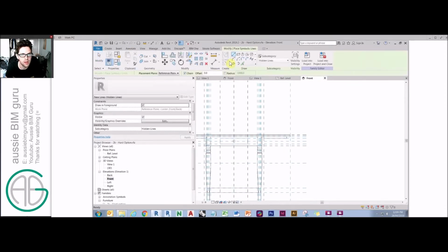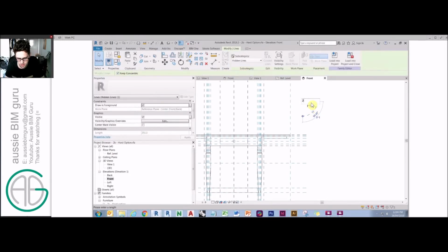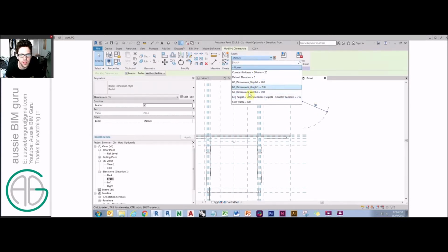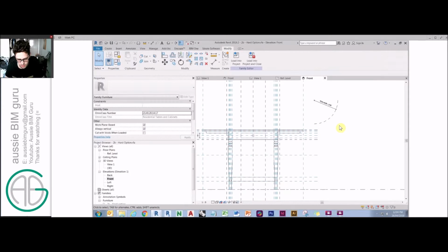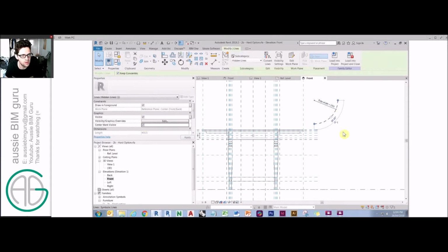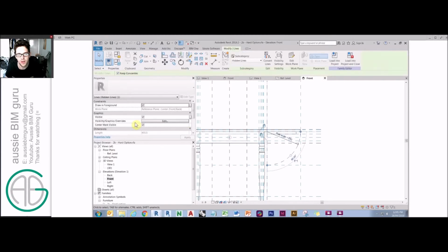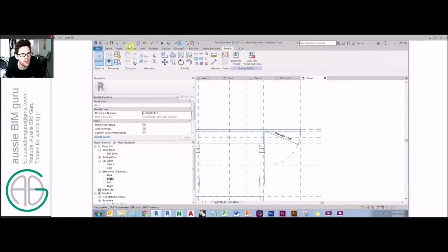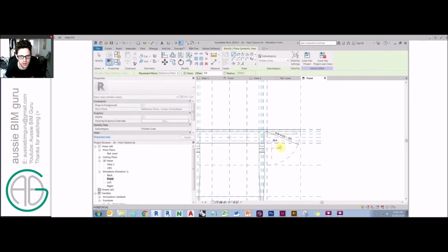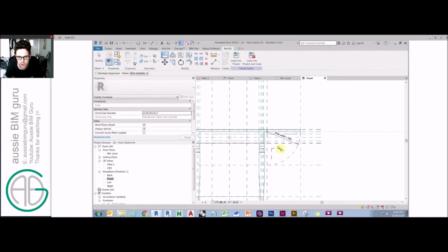I'd do an arc. So we'll just do a 90-degree arc, and we'll just make it the size of the fold. So associate that to side width, so it's connected in parameter. And I'll just turn on the center mark so that we can constrain to here. And it's important to understand that with 2D lines, their center mark actually is a graphic thing, so you do need to turn it off when you're done. And from there, we could look at adding also the swing, just in case it's folded down, and you'll see why we do that in a sec. Okay, so they're all constrained up.